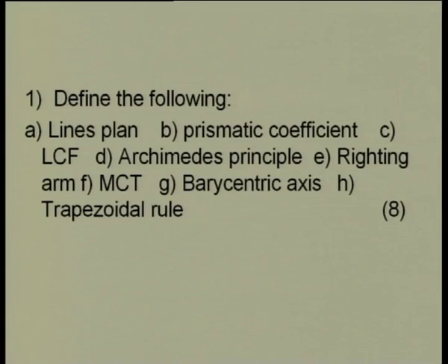Then some people have not written LCF, longitudinal center of flotation. That seemed a little more difficult, a lot of people have left that. So LCF, you know what it is? It is the centroid of the water plane area. That is all you have to write really. If you have written a lot of things and not that, then it doesn't make any sense. So it is the longitudinal position of the centroid of the water plane area.